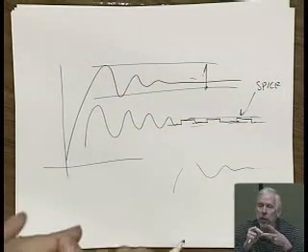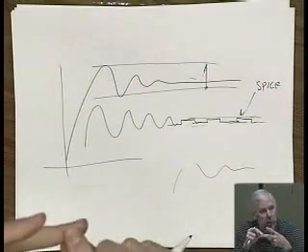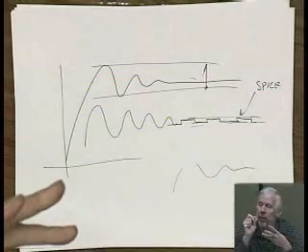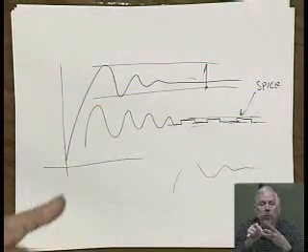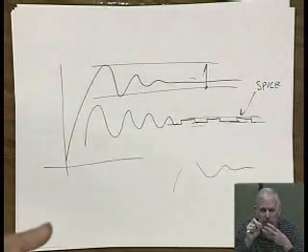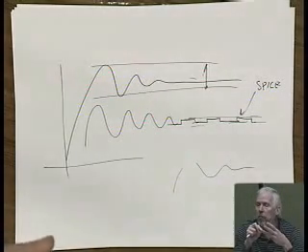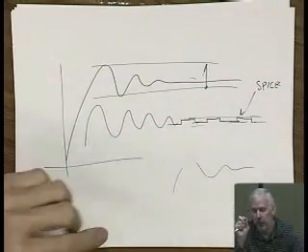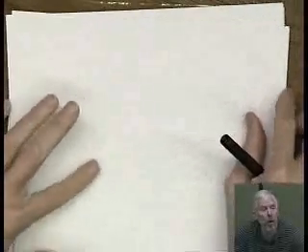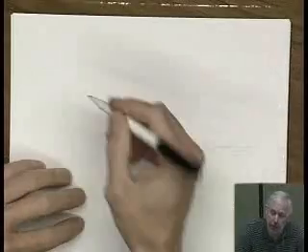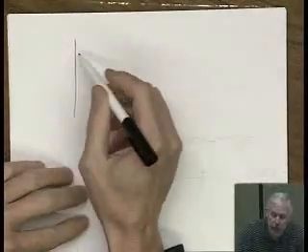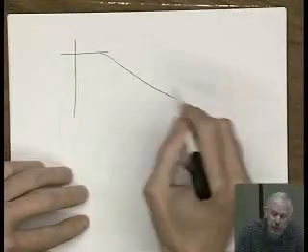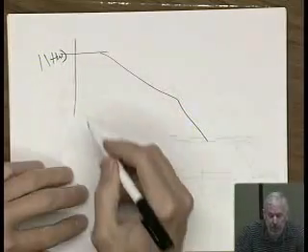It's useful for you to see how the test benches can be worked and how to make use of them. But what you should not do is use those as your only design output. They're really meant to facilitate a little bit of automation. What you should use when you're trying to evaluate what's going on with your circuit, first, for the open loop case, is to plot the magnitude and phase.